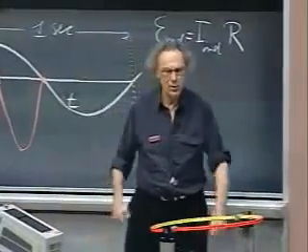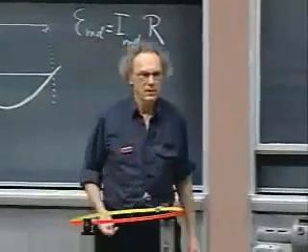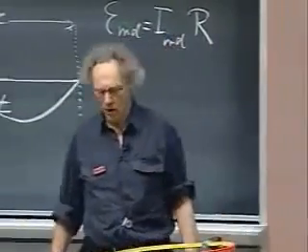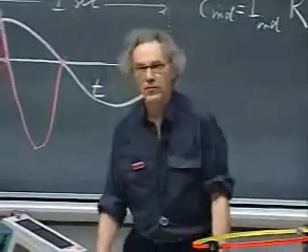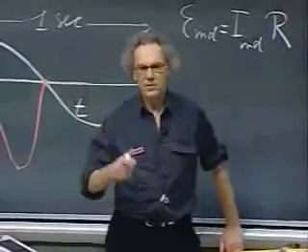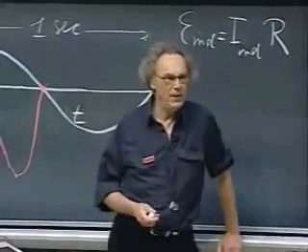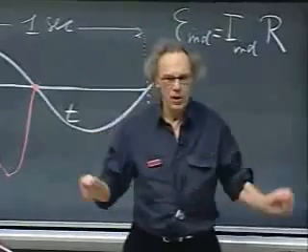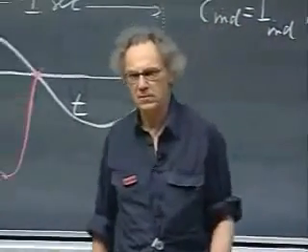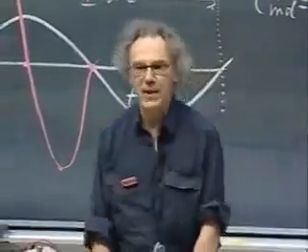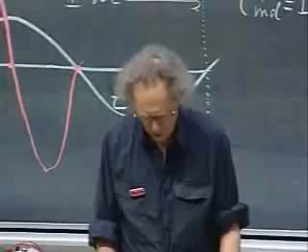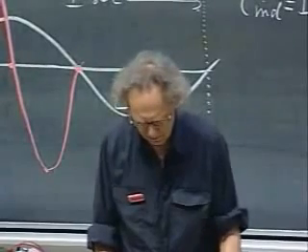No, that doesn't mean that, because filaments get hot, and so they still glow even when the current is 0. They don't cool that fast. If you take a fluorescent bulb, then indeed the fluorescent tube goes completely off and on 120 times per second. And therefore you can use them very nicely as stroboscopes, but of course the frequency is fixed. You can't change the frequency. It's 120 hertz.